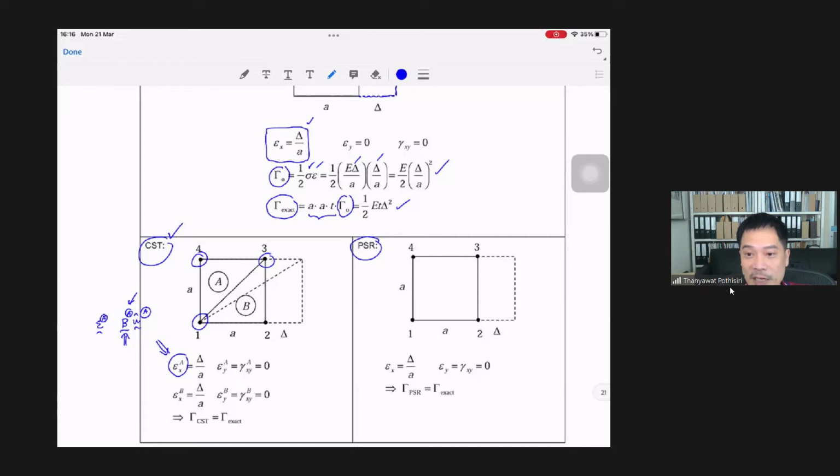And that's what we're going to do in our assignment as well. The B matrix must be computed based on the coordinates of each node. You know all these coordinates, so you should be able to obtain the B matrix for element A. What about U hat of element A?